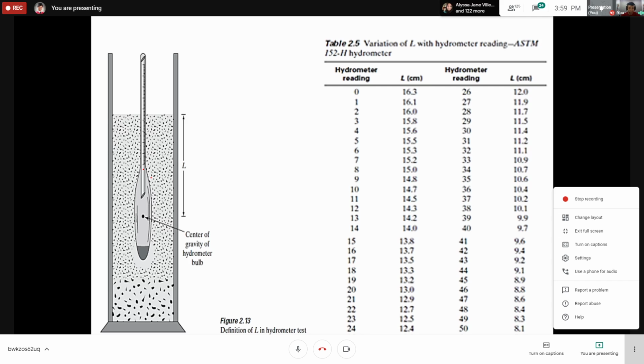So there are different readings for different time periods. From 0 seconds, the heavy materials may already have settled down, so you need to take the reading. Then after 60 seconds, and up until 24 hours or more, you keep taking readings. If you observe the picture earlier, it was still brown, like a milkshake, like a chocolate shake. If you leave it until tomorrow or 24 days or more, the top will be clear and only the soil sediments will remain.